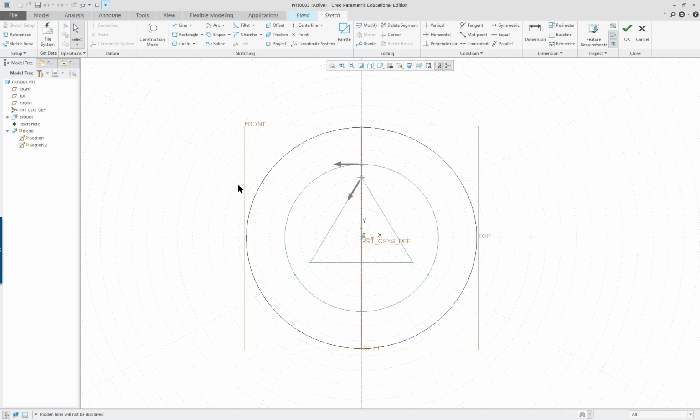And in this case, let's do an arc again. So starting, ending. I'm getting a little sloppy here. I should have put in my center lines, but I'm not going to bother. Like so. Now, one of the things I want to do while I'm here, I'm going to click on this and then change it into a diameter dimension.